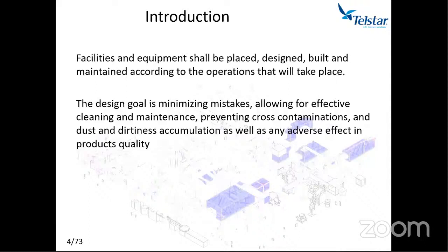With a bad design, it's very difficult to have a completely GMP compliant facility. With a good design, you are helping people to avoid mistakes. Let me give you a good example. If you want to avoid people getting into a clean area and out of the clean area having cross-contamination, you can have a very detailed procedure where you explain that when the light of the access to the chamber is green, you can get in.